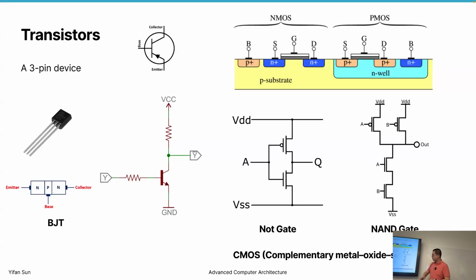What do we use today? You probably have heard of this thing called CMOS. It's called complementary metal oxide semiconductor. Okay, let me introduce this part first. Metal oxide semiconductor. This is the side view of what I would call a gate, but we can just focus on this part. We have a P substrate. Physics. Don't worry too much about physics, okay? Then we have an N well and another N well. Then here is an oxide, right?